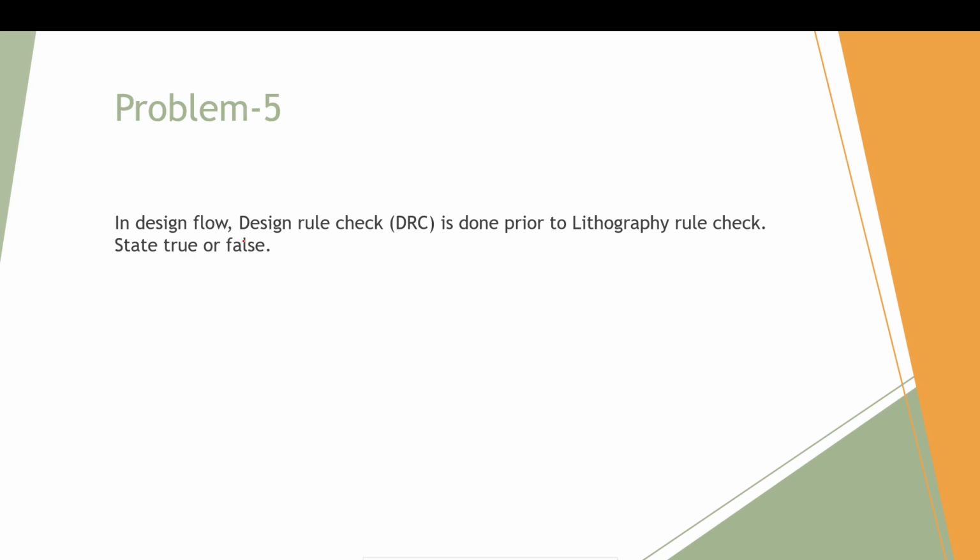So whenever we go for lithography writing, we first give a design. We first have an idea, and based on the idea, we make a layout. This design that we give to the foundry or to the mask manufacturer, we should first see if it is okay to be fabricated. Every foundry will have a process design kit, and that process design kit will give some design rules that we need to check before sending our design to them. So these design rules are checked at the designer's side. This is the DRC that we do.